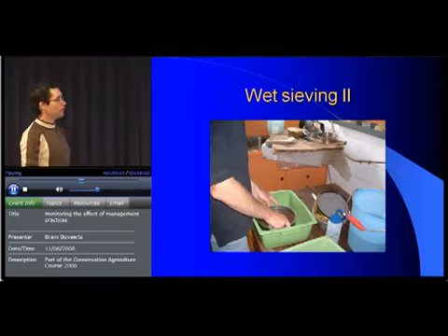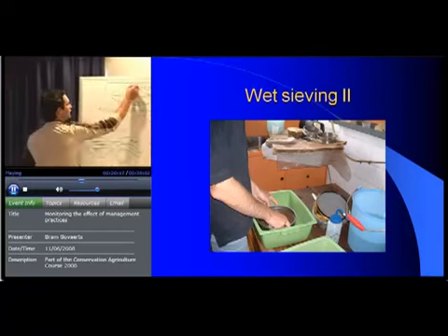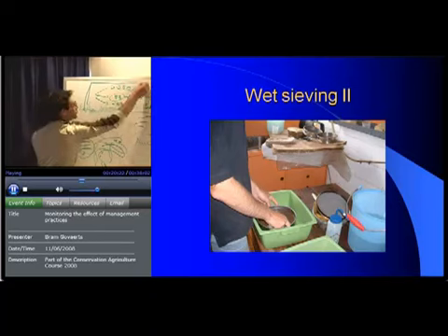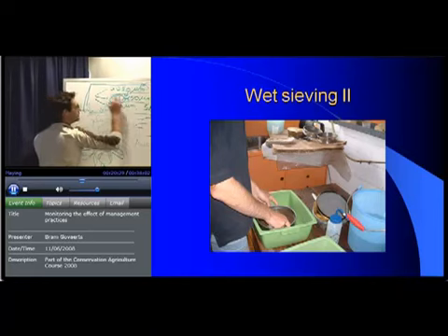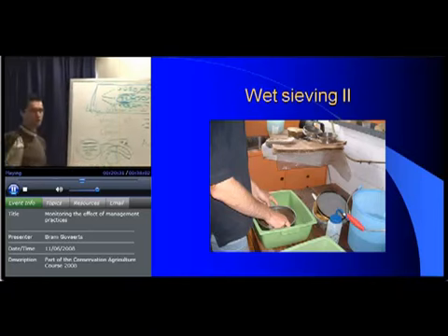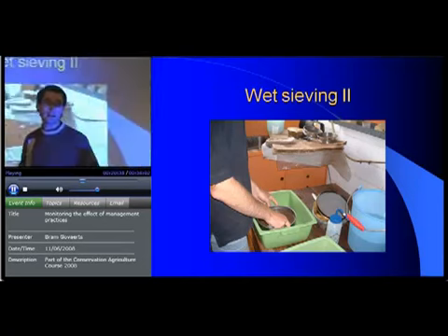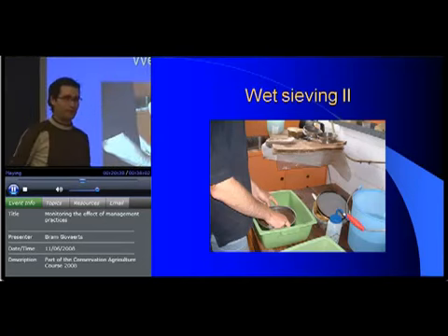The other methodology, if you have less, is doing it just by hand. Big sieve, which sieves is it going to be? 250 micrometer sieve, of course. 53 sieve, so you put the soil first through this sieve. What goes through this sieve goes to this sieve. What stays on top of the sieve is this fraction, what goes through it is that fraction, right? Problem with this methodology, you can see it already, lots of water. So you need big buckets, right?